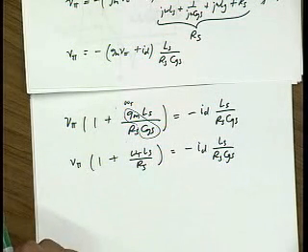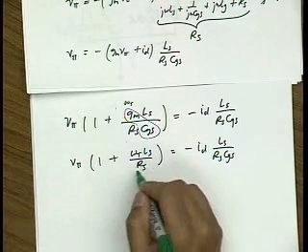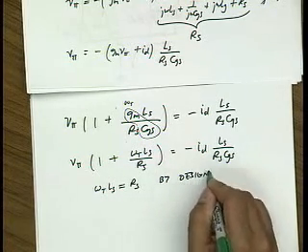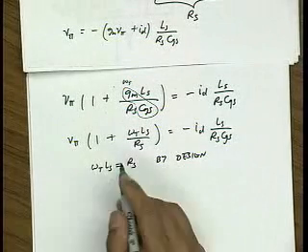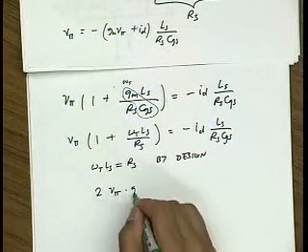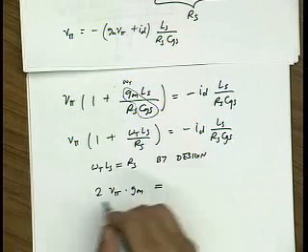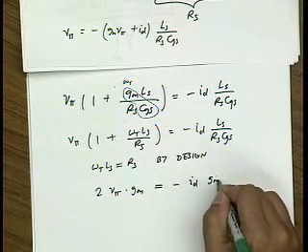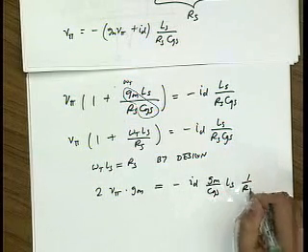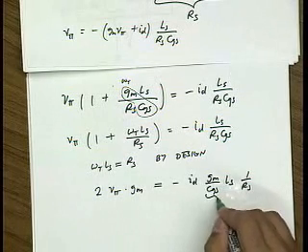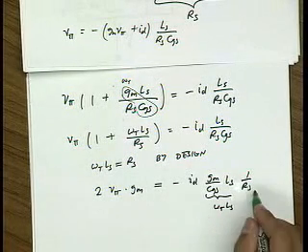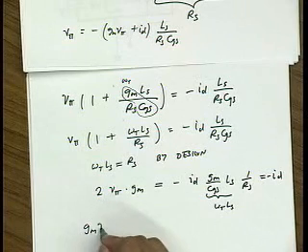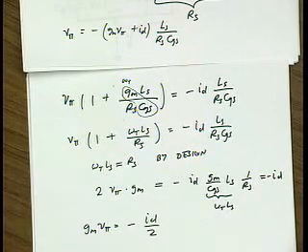And what's omega t Ls? That's Rs, right? So by design, I select Ls to satisfy this equation to give me an input match. So this gives me 2V pi, and let me multiply this by gm to give me the current through that transistor, which is minus I drain times gm over Cgs, Ls over Rs. And again, this is omega t Ls, which is equal to Rs, so this is just minus I drain. So the interesting thing is that gm V pi is half of I drain.